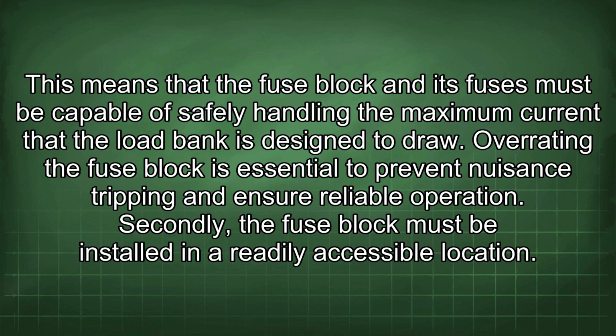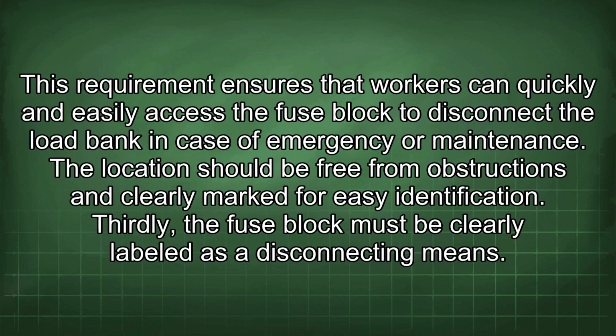Secondly, the fuse block must be installed in a readily accessible location. This requirement ensures that workers can quickly and easily access the fuse block to disconnect the load bank in case of emergency or maintenance. The location should be free from obstructions and clearly marked for easy identification.